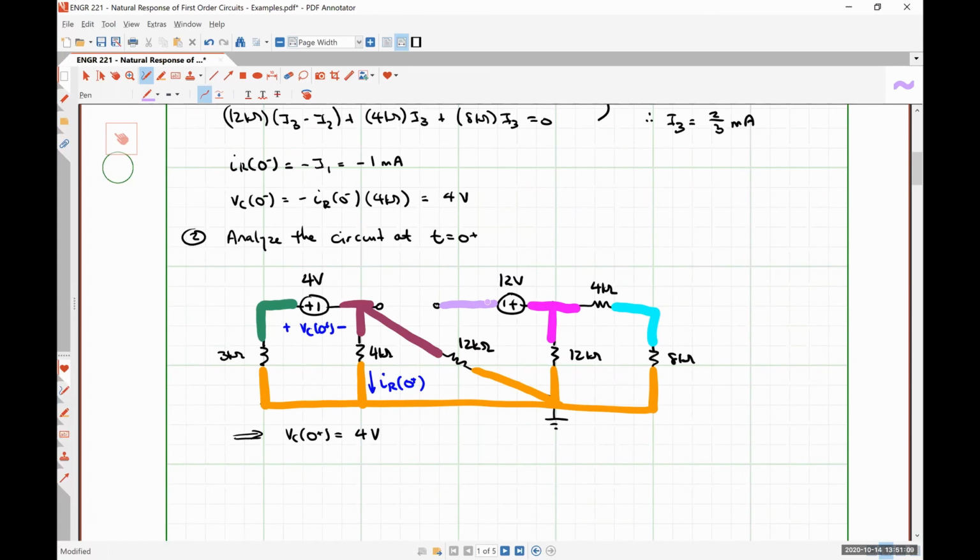Alrighty, so it looks like we have 1, 2, 3, 4, 5 nodes, not including our ground node. So in order to do nodal analysis here, we are going to need to make some circuit simplifications, at least to be able to handle it on our calculator. This particular problem, the simplifications are fairly straightforward. For instance, I can observe that the 4 kilo ohm resistor and the 8 kilo ohm resistor are in series. Anybody disagree with that?